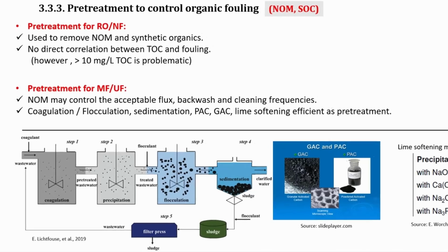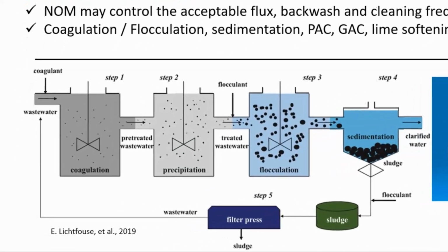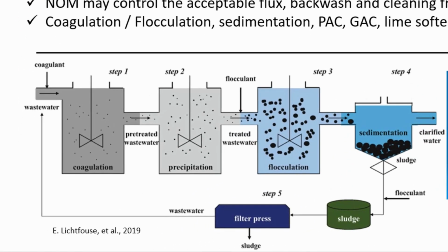In this figure, as a conventional method to remove natural organic matter, as well as colloids and suspended matter, in the first step, after injection of the coagulant into the pipe, using a stirrer, mixing and contact time lead to the formation of the floc. In the second step, a part of the floc is settled on the bottom. Adsorption of polymers as a flocculant and bridging, called flocculation, and precipitation with entrapping of particles is done. Then, in the clarification, the formed floc can be settled.